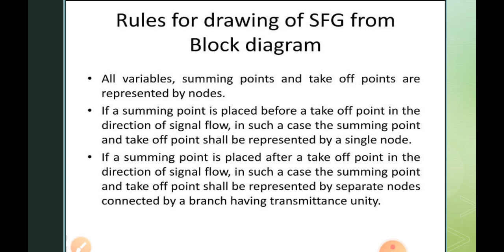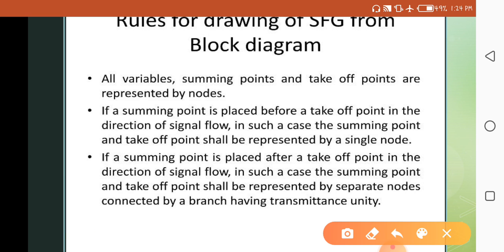Now, rules for drawing an SFG from a block diagram. So these are the rules. First of all, in a block diagram we discuss the summing point and the takeoff point. When the summing point and takeoff point represented in a block diagram are converted into an SFG, the summing point and takeoff point are represented by a node, that is a point.